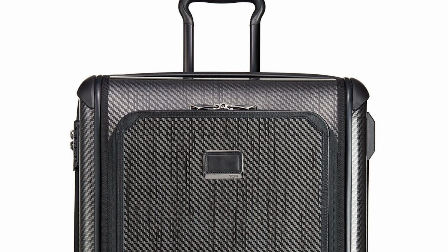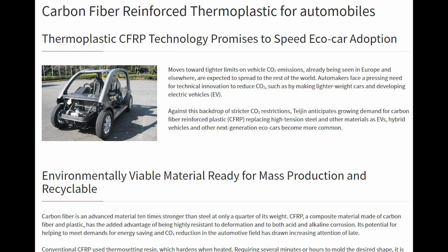I've been reading papers on mixing the thermoplastic with carbon fiber. So they'll do transitional layers, as in one will be thermo, one will be carbon, one will be thermo, one will be carbon. And they're finding like 20% reduction in weight for similar strength. I was very interested in that, and I was trying to get my manufacturer to do that, but they can't bond the two together. Apparently, the process of actually sticking the thermoplastic layer to the carbon layer is the problem, getting it to laminate together.